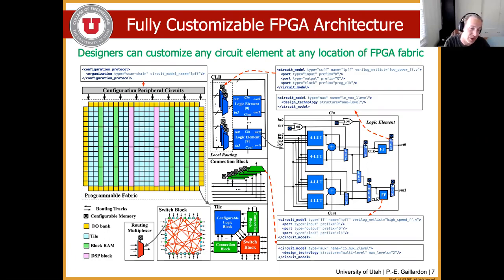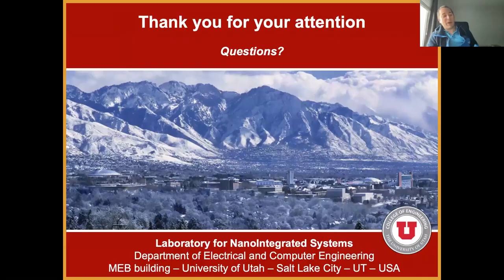Actually, one more question. Are you doing another tape-out on SkyWater? Yes, we're currently working on a few new tape-outs. We are working on some heterogeneous tape-outs, with DSP plus homogeneous fabrics. You'll love that one: DSP plus OpenRAM plus homogeneous fabrics. That's our current objective on SkyWater.